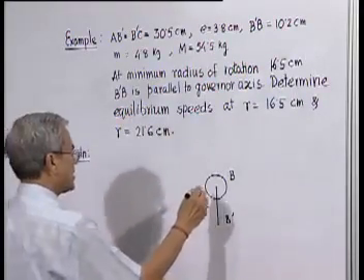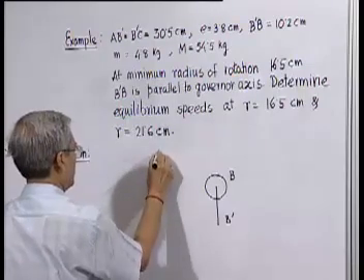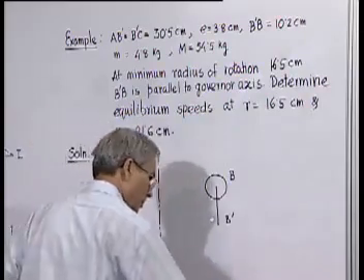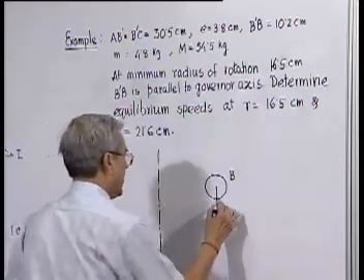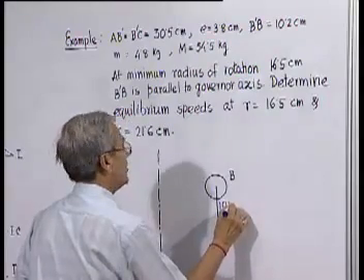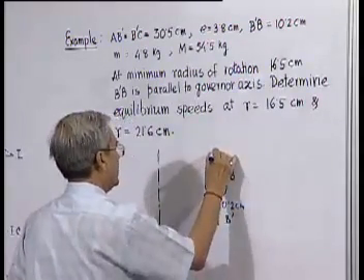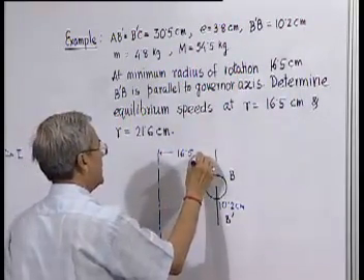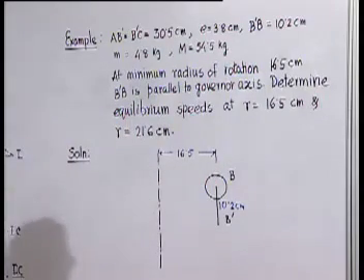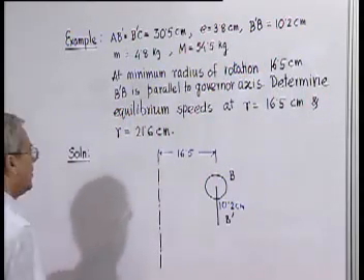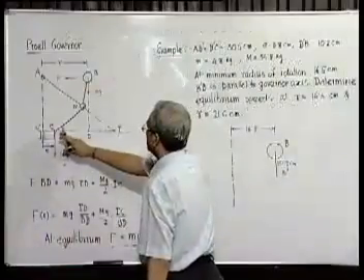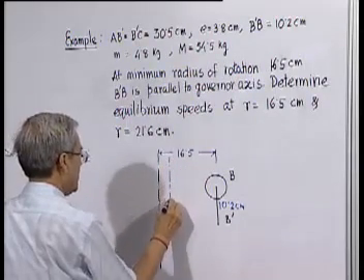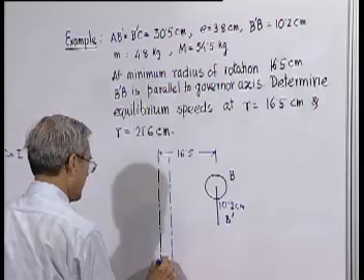Now we know the distance of this ball from the governor axis. So this length is 10.2, and this line we draw is at 16.5. That is the value of r at this instant. Now draw another line on which point C will be located, and we know that it will be at a distance 3.8 centimeter from the governor axis.